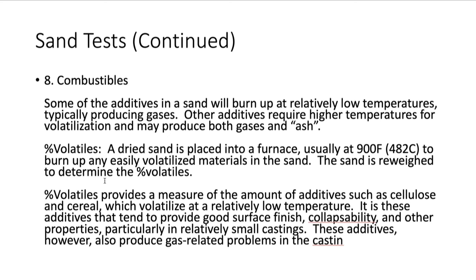Combustibles, what is that? Earlier we talked about putting some sort of additive into the sand that's going to give off carbon monoxide or somehow break down and keep it from sticking. But we want to know how much is still in there. One of the ways to do that is to wash the sand, get all the clay out of it, and then dry it and burn off the rest of it.